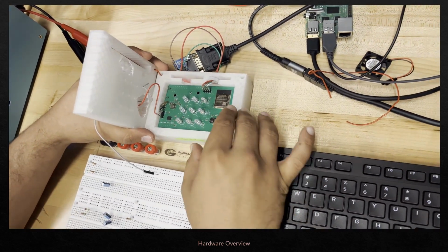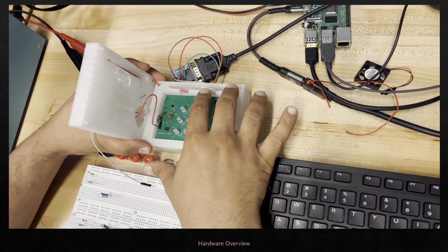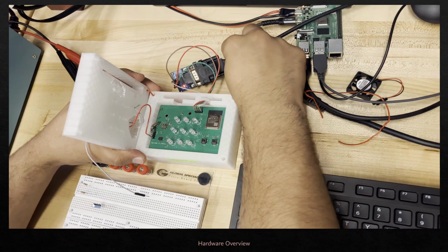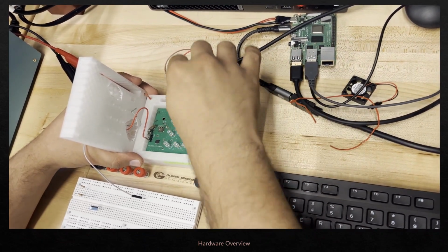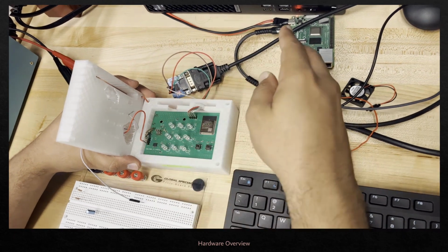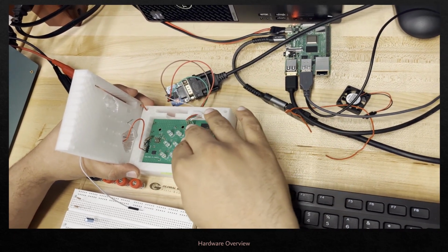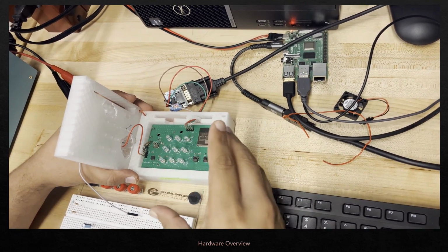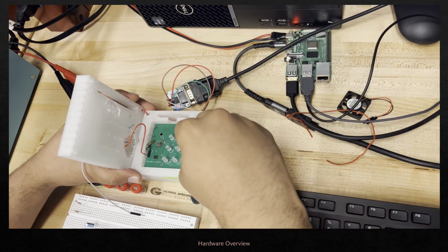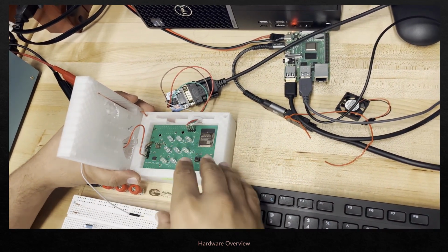So with this, what we have is these 4 pin headers, which are connected to the ESP32. This will be used to connect to the RS232, which is then connected to the Raspberry Pi over here. The RS232 is responsible for the communication between the Raspberry Pi and ESP32. That's how they will be communicating with each other, and the communication will be sent over to the ESP32, and then the LEDs and sensors will be programmed through there.